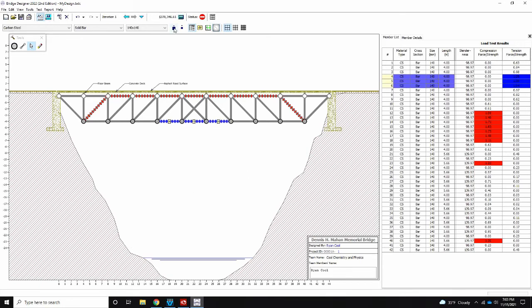of those members. And I can either, again, go to the menu, or I can click the size up and size down. So size up and size down. I'm going to make them all 1 bit bigger. So they are now 150 by 150. I could now go in and change all the compression ones, but for now I'm just going to see if that fixed those three members.